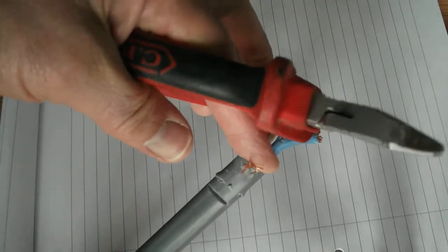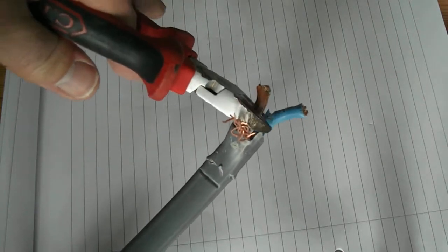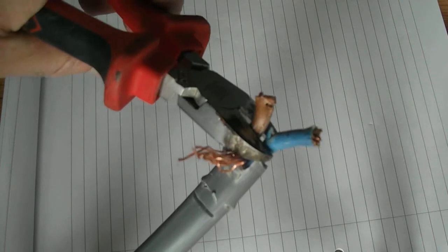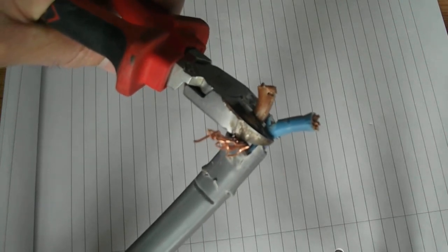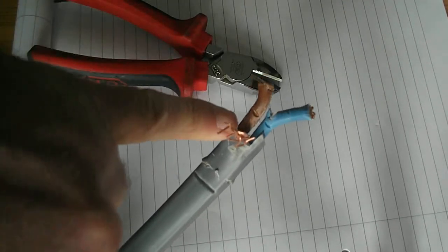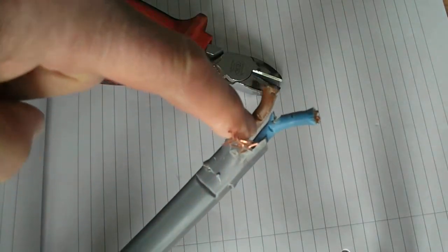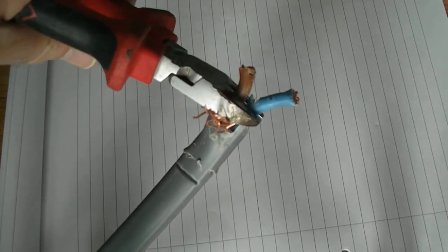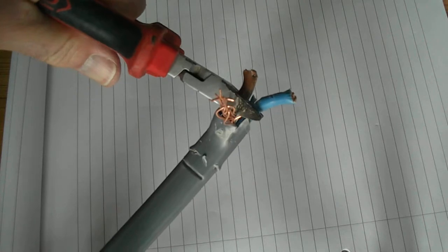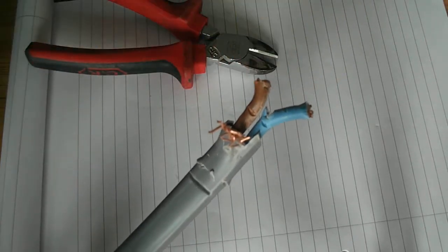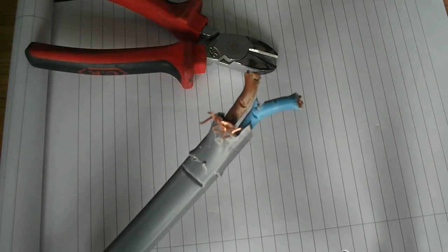Similarly, you might get a dead short between two phases, and if I squeeze those gently, as I'm squeezing harder and harder, should get something. Here we go. And you can see the insulation just looks a bit dented there, but because I squeeze hard, it digs into the conductor and creates a low resistance path, which produces a fault.